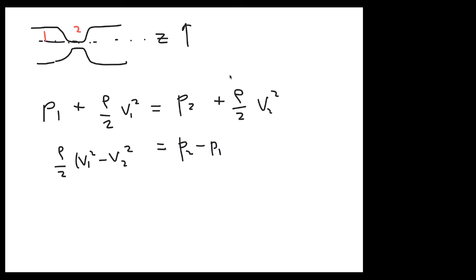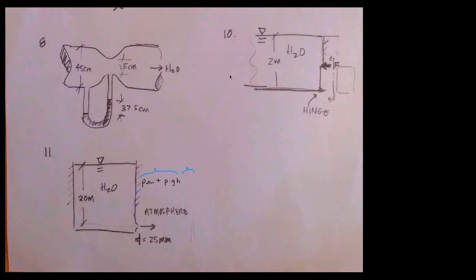And we know that this pressure difference is given by, going back in the slide, this difference in pressure on the Venturi tube here. So we know that is equal to rho of the mercury times gravity times the height of that mercury.